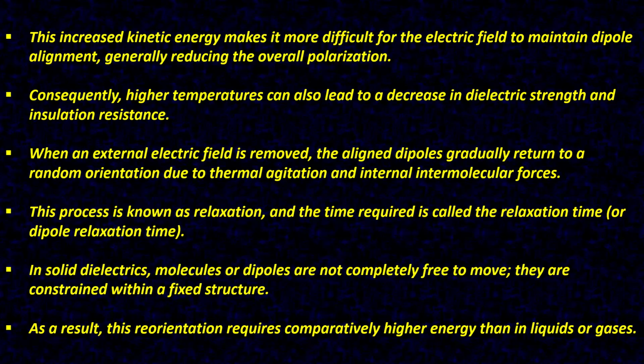Mainly in solid dielectrics, molecules or dipoles are not completely free to move, unlike liquid insulations, that is oil. They are constrained within a fixed molecular structure. As a result, this orientation requires comparatively higher energy than in liquids or gases.